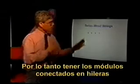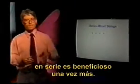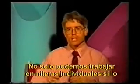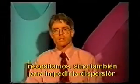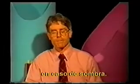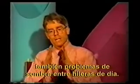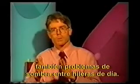So having our modules wired in series strings is beneficial once again. We're able not only to work on individual strings if we need to, but in the case of shading, we not only can prevent leakage at night if we need to do that, but we can also prevent interstring shading problems during the day.